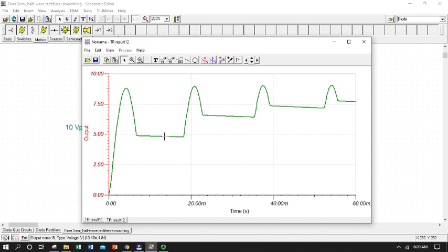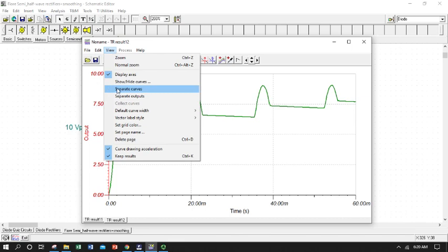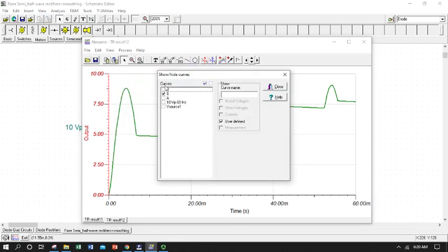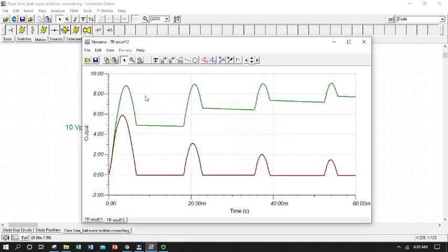But you'll notice something. We do have a flatter line between, and it's changing from period to period. If we were to go ahead and display our charging, go back to the chart. This is the charging current through that capacitor. By going to a much bigger capacitor, what we did was we gave it more capacity, literally, to hold charge.